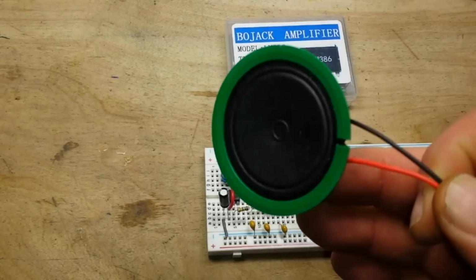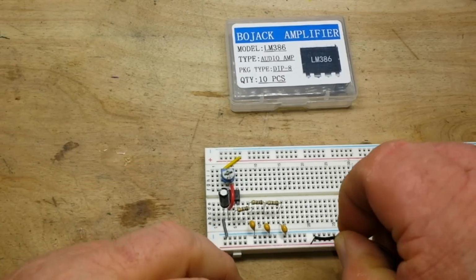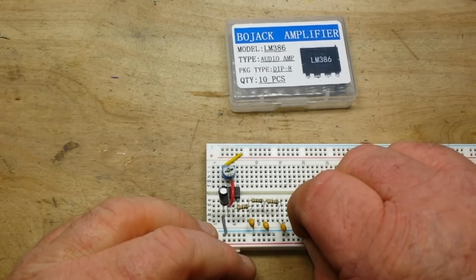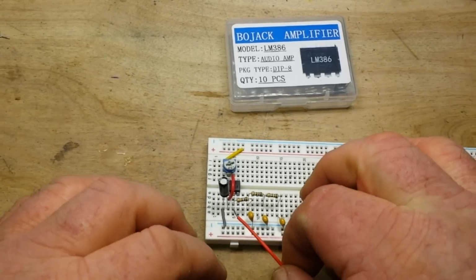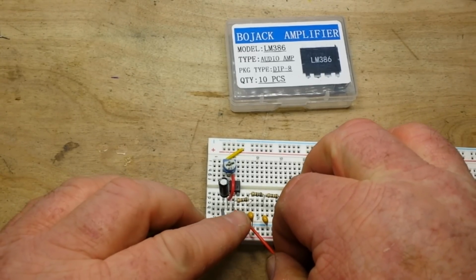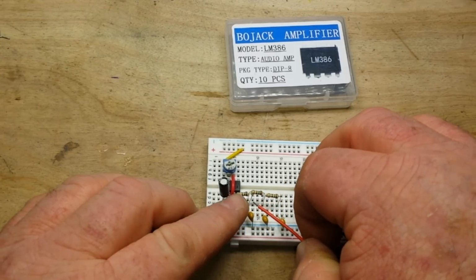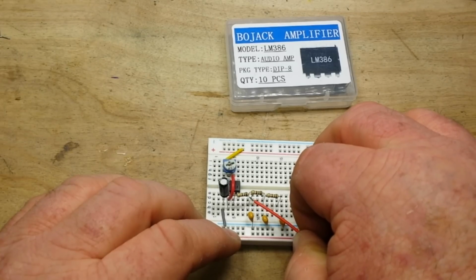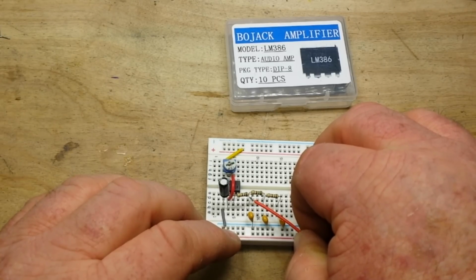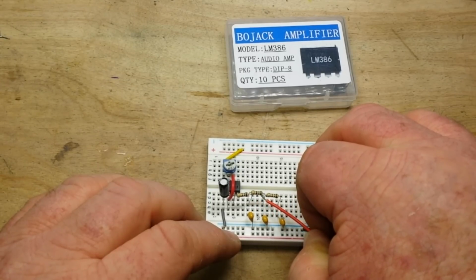All we need is a speaker. So we'll plug the negative lead of the speaker into our negative rail, and we'll touch it to pin 3, and you can hear the 1 kilohertz tone. We'll touch it here after the first stage. It's much quieter, more of a sawtooth, smoother. It's a triangle wave there.